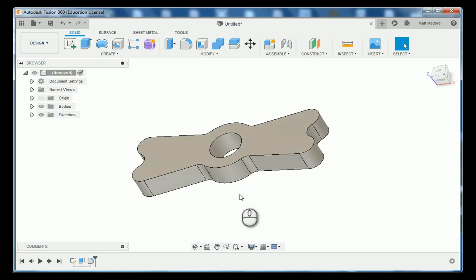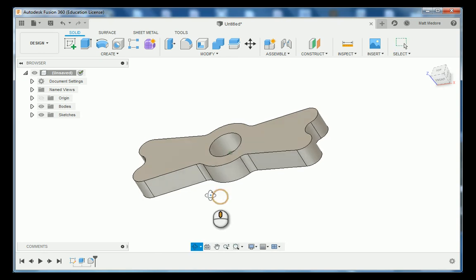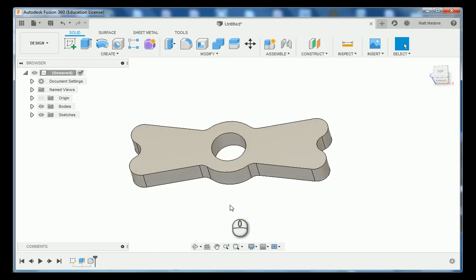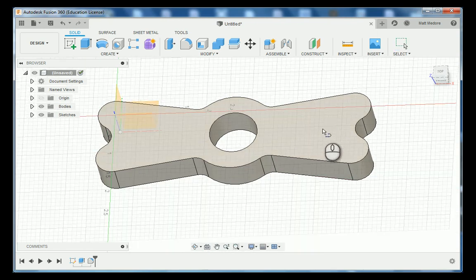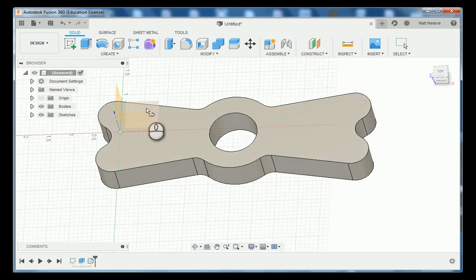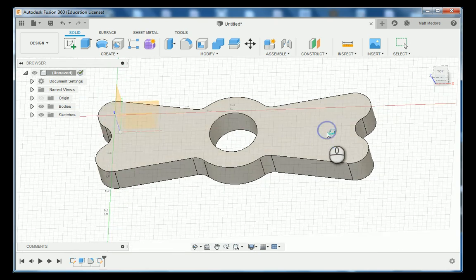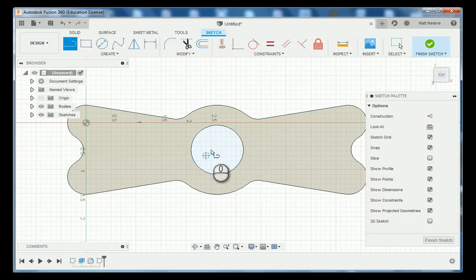Moving on to sheet number 2. Sheet number 2 has this revolve cut around it. To set us up for this revolve cut, we're going to put some construction geometry in. We're going to go L on the keyboard for line. We're going to click on the top of the part here. Be mindful you are not clicking on these planes over here. So click on the top of the part. We're going to go concentric to the bore here and go straight up with this line.